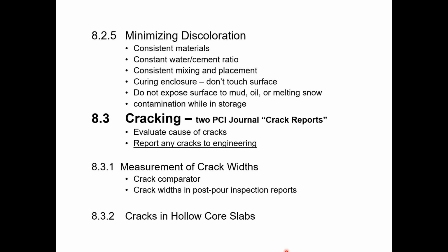And anytime you have cracking like that, you want to report it accurately. So give maybe a little diagram, a little sketch that shows, well, here's the double T, and the crack ran from the bearing point all the way up the stem about 5 feet. Give a dimension, kind of show where it runs, so that those cracks can be evaluated.